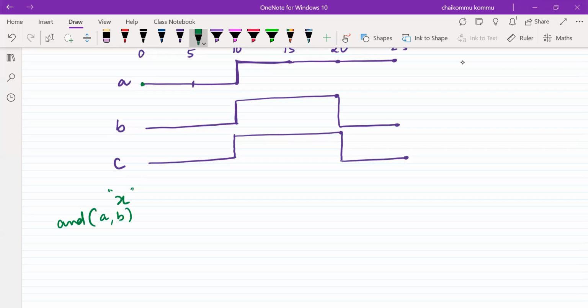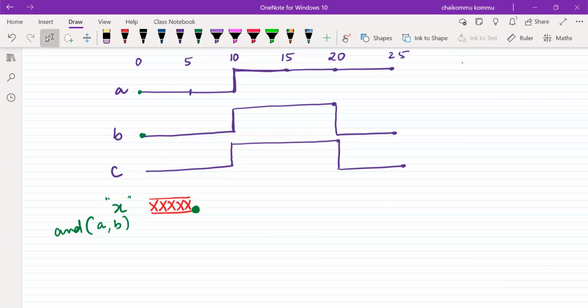So we started off at 0 nanoseconds of time. For the time being, we don't want to consider C, only A and B. At 0 nanoseconds, what can we observe? A 0 value, but the 0 value is not directly assigned as an output, it has to wait up to 5 nanoseconds. What is the value until then? It is unknown. So at 5 nanoseconds, the 0 will be assigned. Now this 0 will be available as long as there is no change in A and B.